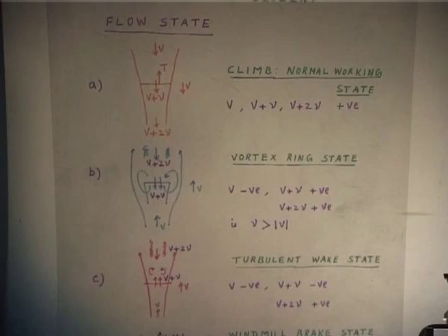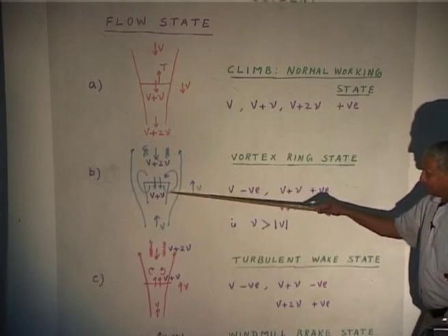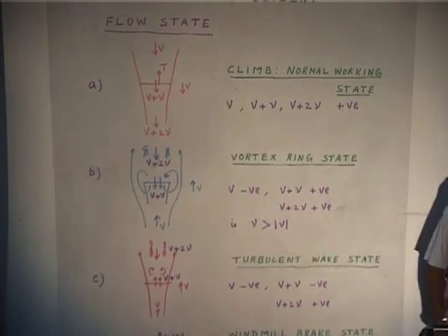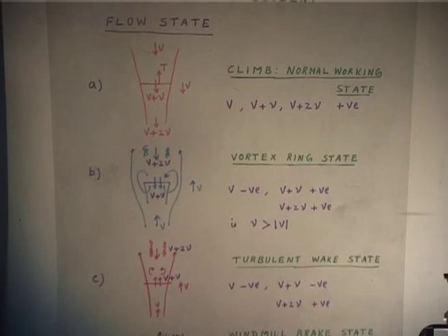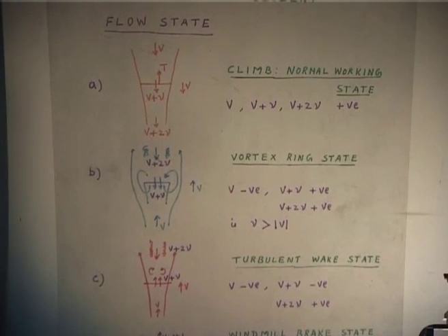Now, you see what happens is the flow is coming, this is pushing. One flow is coming, something is going down, it will go around the rotor disc, and you will find big vortices will form. And then once the strength becomes big, the vortex will detach and go up, and another one will form. That means the flow inside the slipstream is not all in one direction, it is going to be a mixed flow.